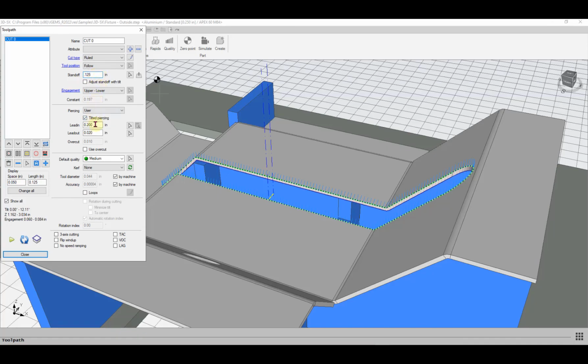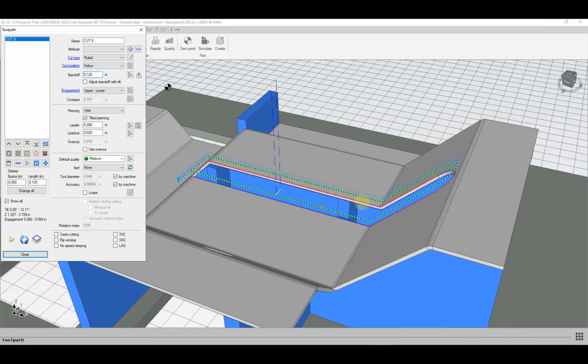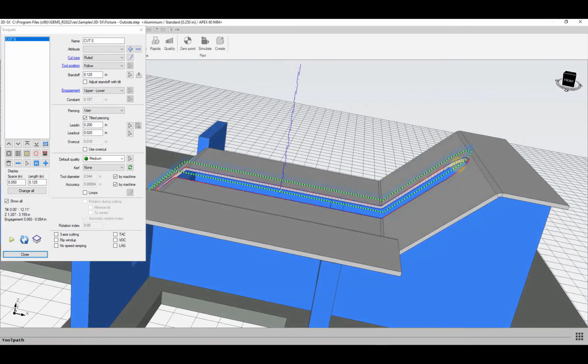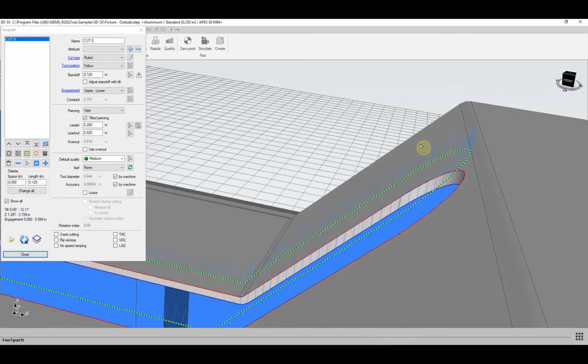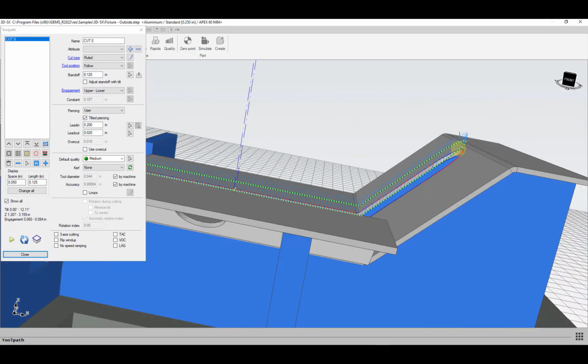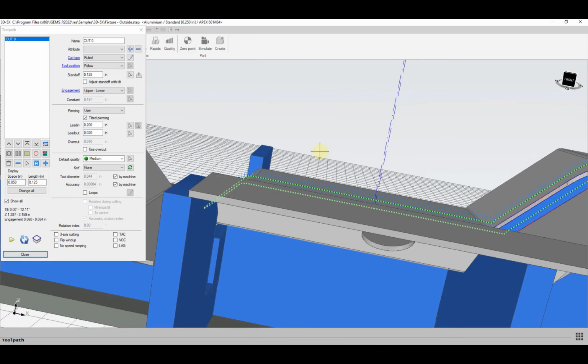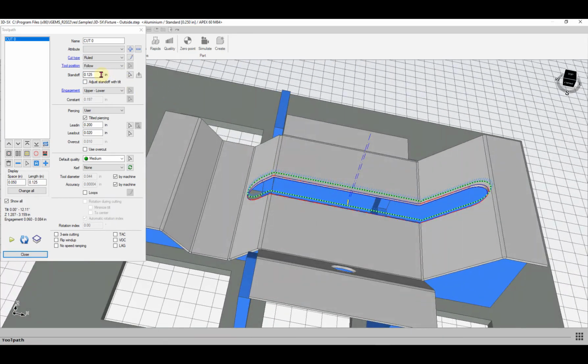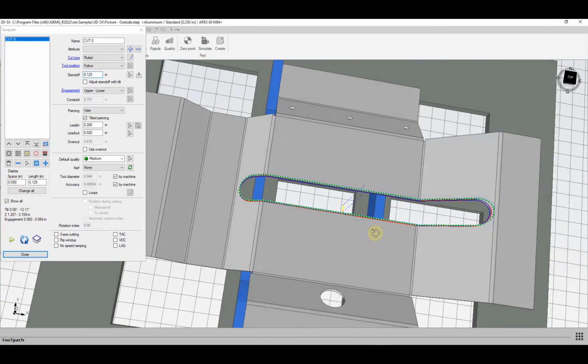So if I put 1/8 inch in here, that would add an 1/8 inch to the normal 1/8 inch that we're off our material, so we'd end up being about 1/4 inch off the material when we cut this. And then if you feel comfortable with things later on, you can drop that down some. So that's what the standoff can do for you.